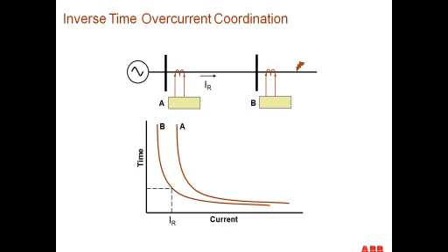What is the time delay difference required for the two relays in operation? On talking about our coordination between these two relays, that typically is a function of the level on the system. Is this a distribution system? Is this a transmission system? The difference in operating time between the two relays would be called the coordinating time interval. On the distribution system, this coordinating time interval is normally in the area of seconds, like 15 seconds or so. On the transmission system, this coordinating time interval is in the matter of cycles, like 15 or 30 cycles. So it depends on where you are in the system what that coordinating time interval would be.